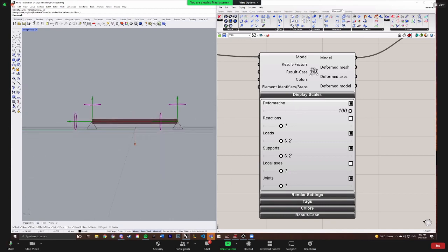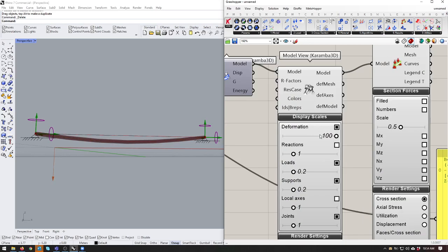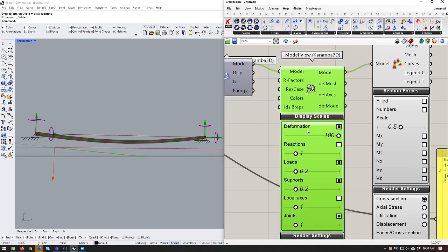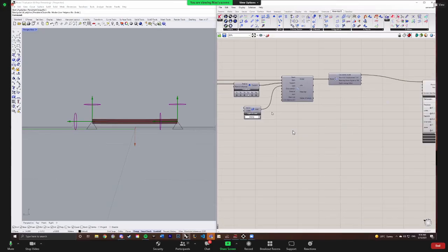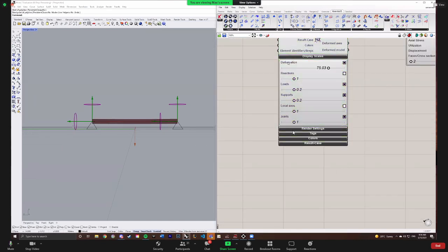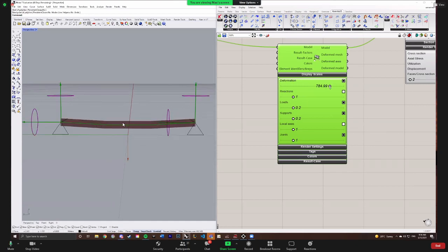Look, if you double click the little node of the slider, that little circle, that then lets you control the minimum and maximum. So if you set that to like 1,000, there you can see that deforming more. So you do have a deforming beam.